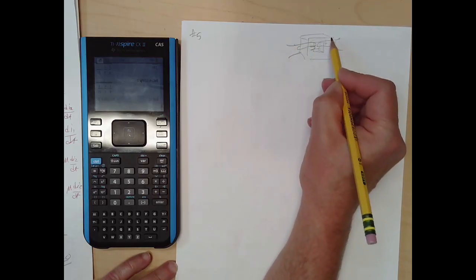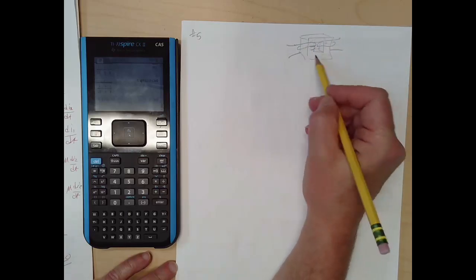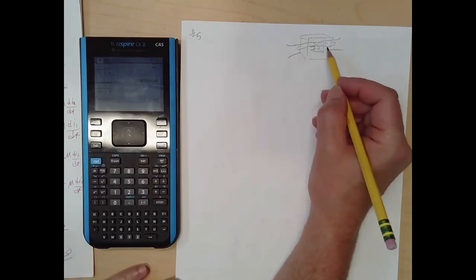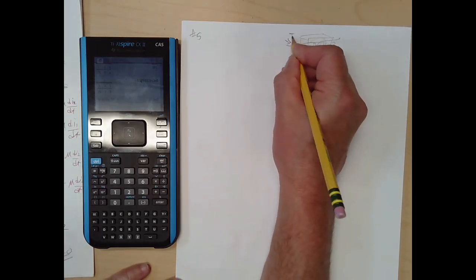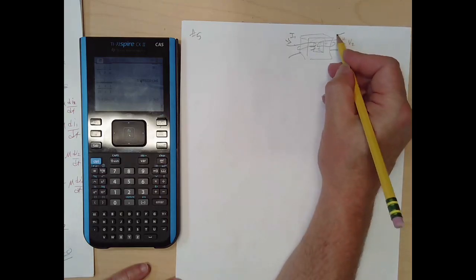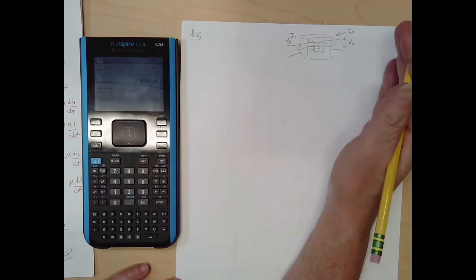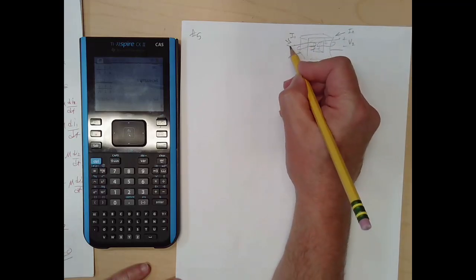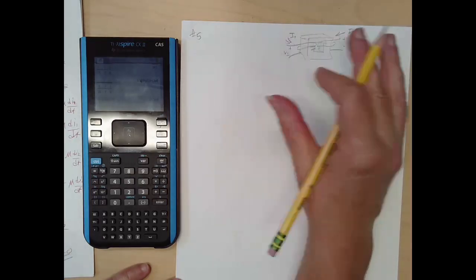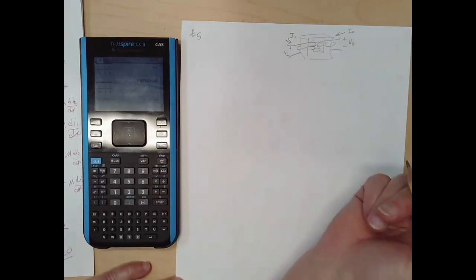All right, so if we're causing a flux, causing magnetic field, causing a flux, the coils basically feel each other through the magnetic core. The same field is interacting with both coils, and so they have a mutual interaction, and so a current over here, for example, can cause a voltage over here. And vice versa, if we push a current through over here, or changing current anyway, it's all V is L di/dt, right? It's all inductor kind of things, but it can cause then a voltage over on the V1 side. So we call it mutual inductance. The coils, one coil can get voltage from the other, right? A mutual effect because they're on a shared core of some sort.